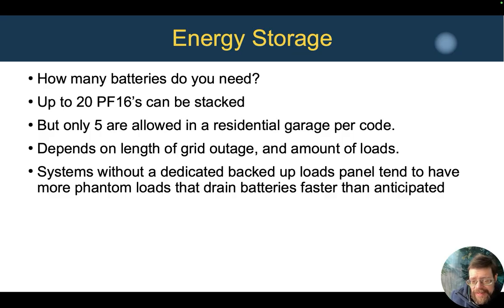And as we discussed, for houses where we don't select just selected loads, but back up everything, we tend to have a lot more of the phantom loads that drain batteries a lot faster than we anticipated. So even if we don't have electric heating loads on there, just random phantom loads of stuff that wasn't that important but just happens to be on there will tend to drain the batteries more.